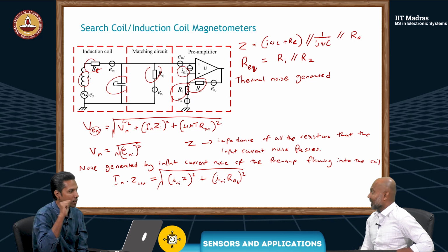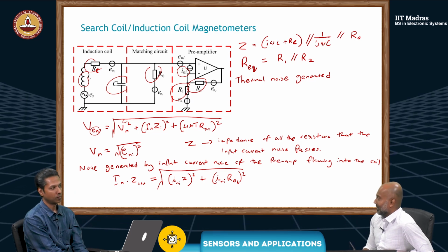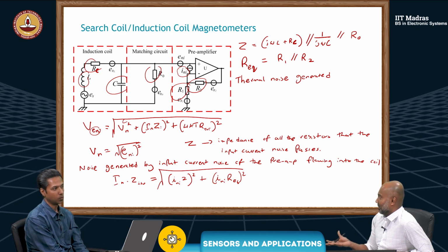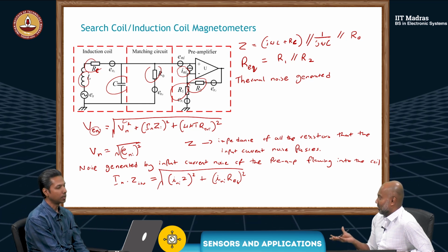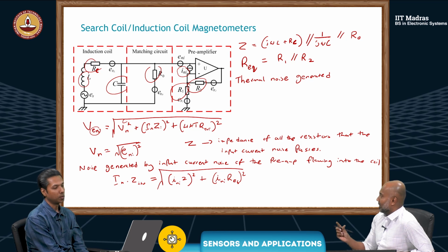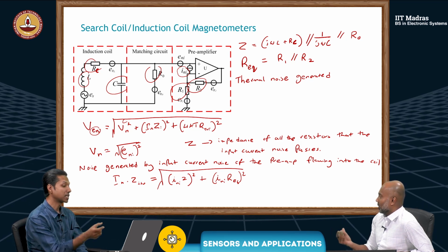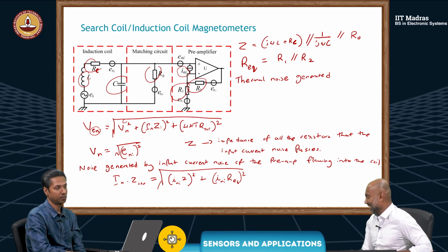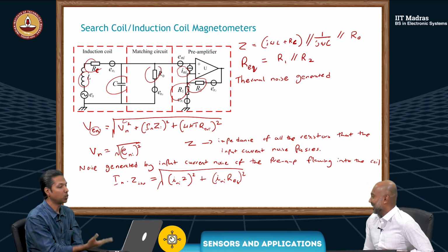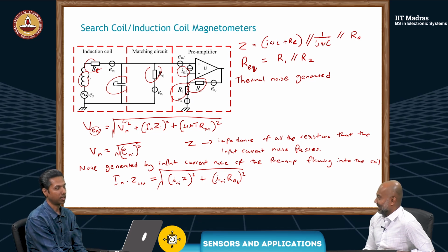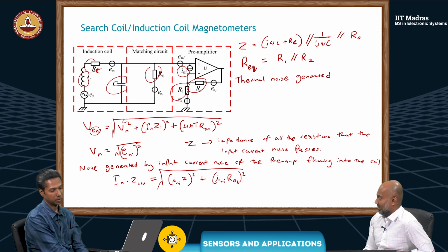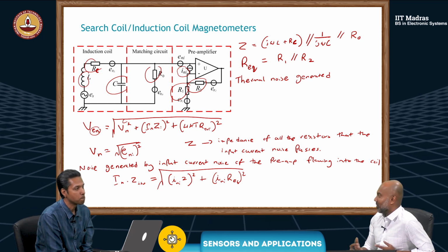Ideally, you would want to keep the noise low. But if the resistor value is very low, then the current flowing through it will also be more. So there's a trade-off, because the op-amp may not be able to supply that much current. Then it's a problem. So we'll have to look at both aspects and somehow find a balance.